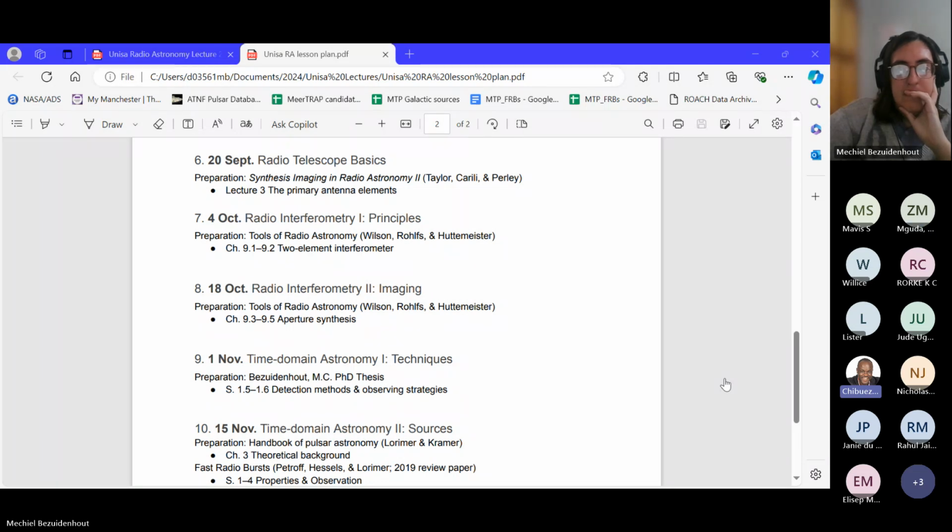So what is happening is you may be integrating for 8 hours on a source, including your calibrators, where you drive the antenna and integrate maybe for 2 minutes, then come back to your source. Each signal coming in is clocked within a nanosecond scale. Yes, otherwise you cannot correlate the data. So you correlate with that clocked signal.